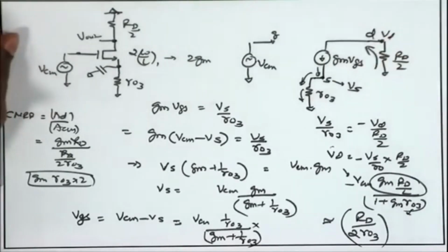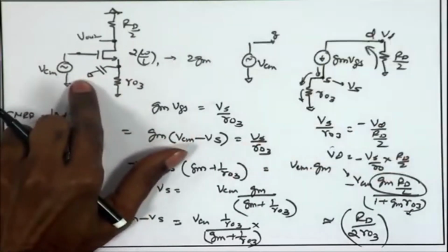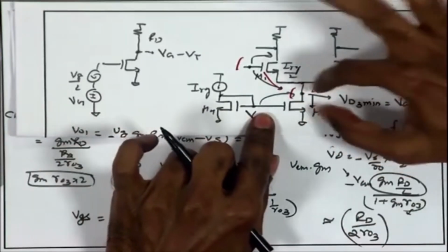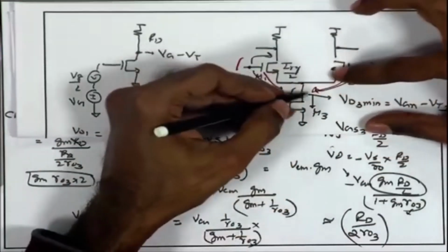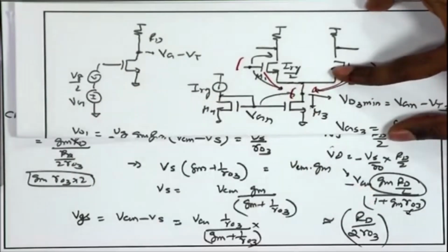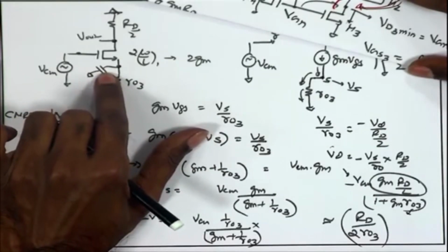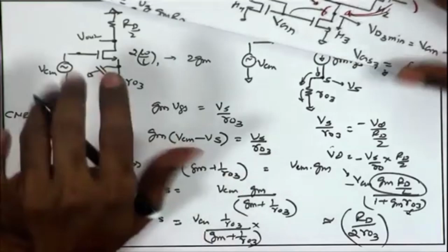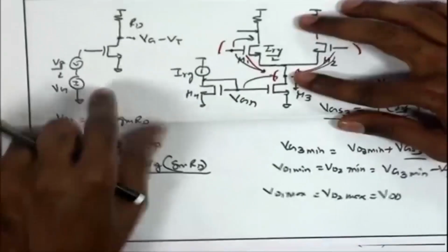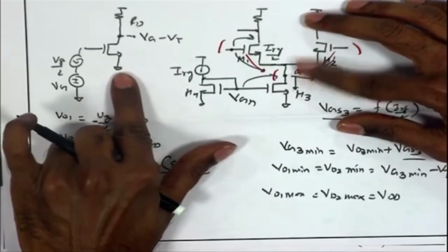Frequency analysis, for the common mode we briefly discussed what is going to happen if you make the M3 large in order to have a larger L, or in order to have a smaller headroom, that is going to increase this parasitic capacitance, and again it is going to reduce your common mode rejection ratio. That is an undesirable thing. Regarding differential case, the circuit is same as what we have analyzed in the common source example. So, we do not need to talk a lot about the differential case.